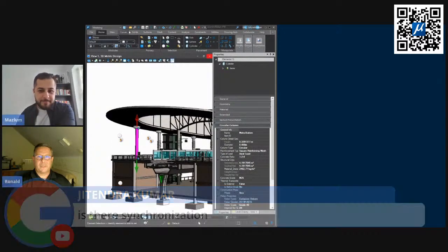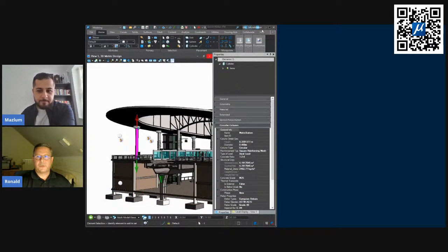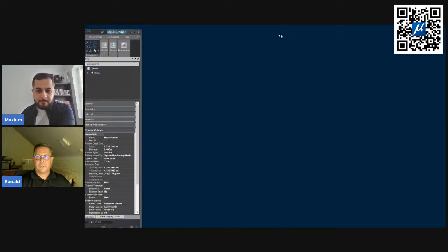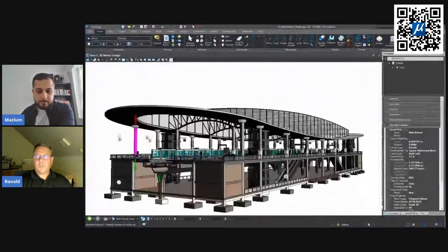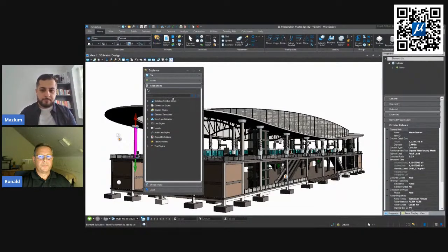Yeah. It looks like synchronization of these workspace settings or whatever. Usually, if this is the question, the workspace and the CAD standard settings I showed you in the Explorer, for example the resources, are not stored locally on your machine. They are on, for example, a network drive where everybody has access, or they could also be part of cloud services or cloud storage. You can share this using a cloud service, and these settings should be there only once.